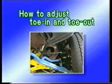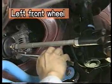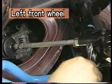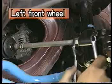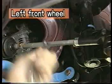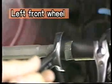If toe in or toe out are not within specification, adjust them. To make an adjustment, remove the boot clips and loosen the tie rod and lock nut. Turn the left and right tie rod ends an equal amount to adjust the toe in and toe out in accordance with the specification given in the repair manual.